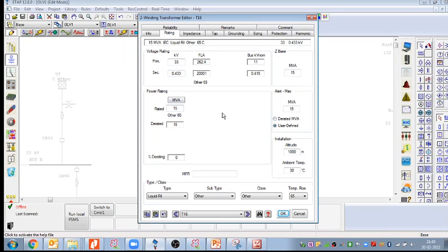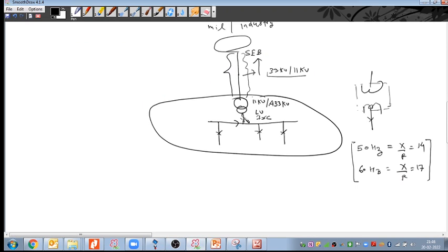Okay. Now my question is: how much power rating can we take for this kind of industrial plant? How much power rating of this transformer can we take? It is not decided only by the industrial load, but there are some electrical limitations also. If their load is increasing, then they do not take 11 kilovolt. They will take 33 and step down to 11.